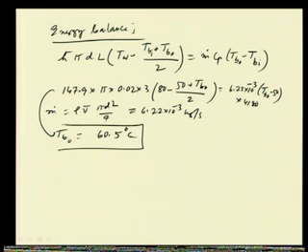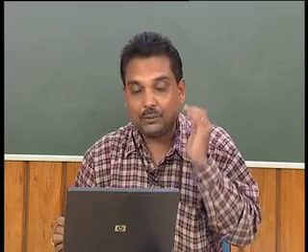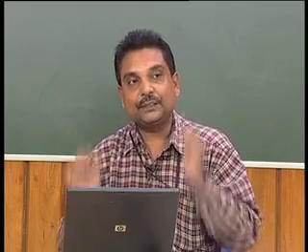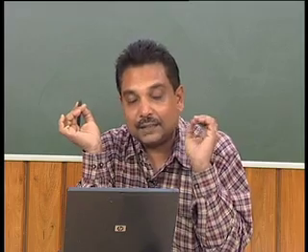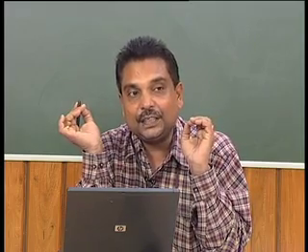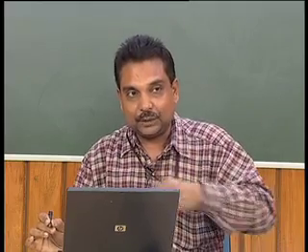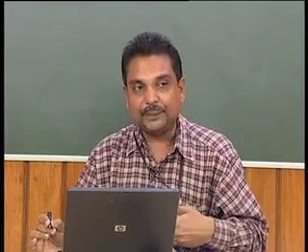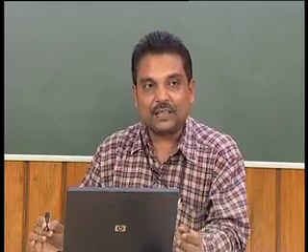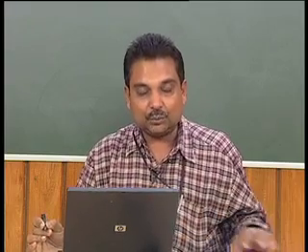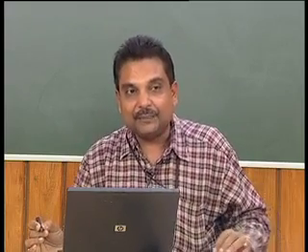Now, this T_bO is the exit temperature of the fluid which is being required, but all the calculations we have done used the properties at inlet conditions. So, we have to now update the properties based on the actual exit conditions, because we have to evaluate the properties at the mean bulk temperature.